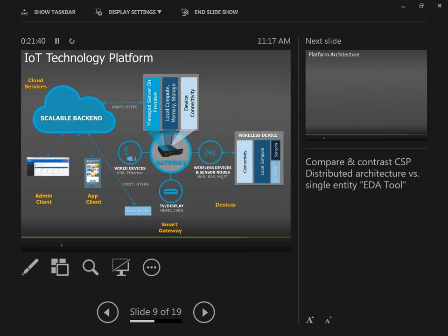So as far as the basic type of added value a gateway brings, obviously the gateway, because it has multiple radio, multiple physical interface, allows a first level of aggregation. So the devices can be of various types. They can be Bluetooth, or they can be Wi-Fi, they can be Ethernet or USB. The gateway will basically aggregate, normalize those data, and be in the situation to push them to the cloud. So this is the aggregation kind of